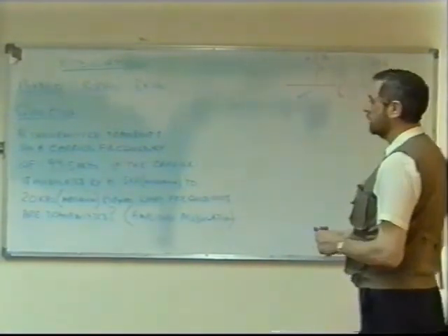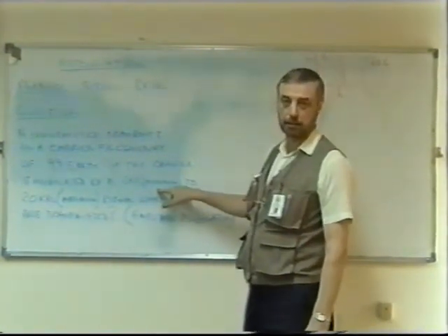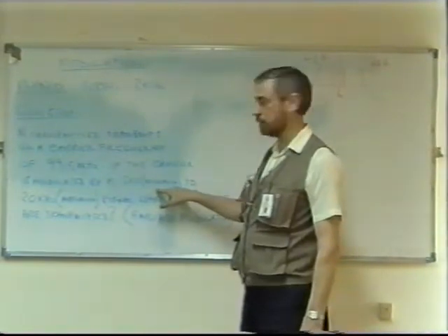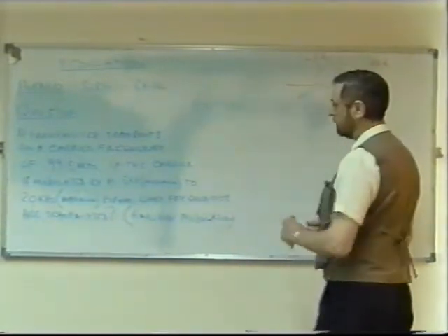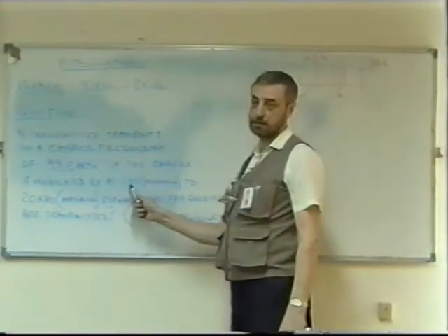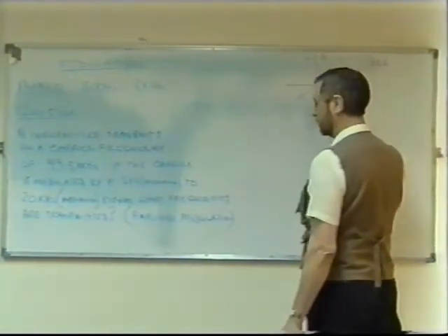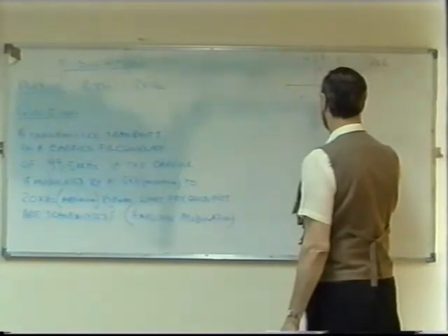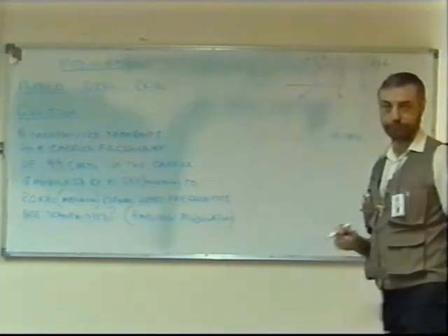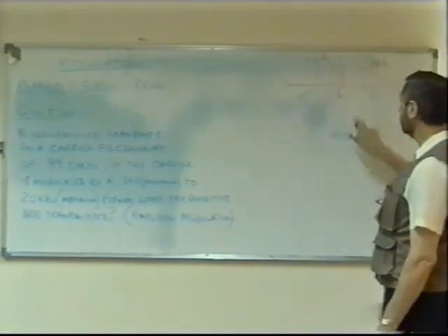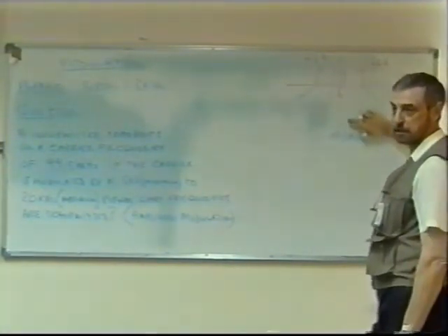So first of all, let's choose the lowest frequency. It says here 5 kilohertz is the minimum frequency. Nothing less than that will be transmitted or used for modulation. Maximum 20. Let's have a look at this one first, the 5 kilohertz. We know FC is going to be transmitted for a start. That's one of the frequencies, 99.5 megahertz. Now this frequency plus 5 kilohertz, isn't it?